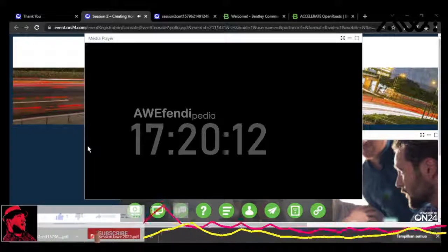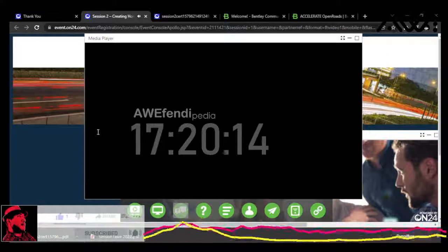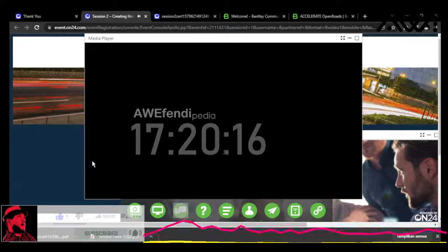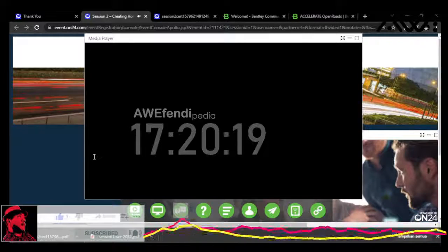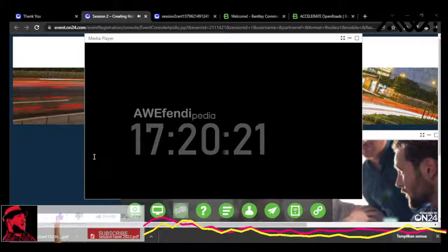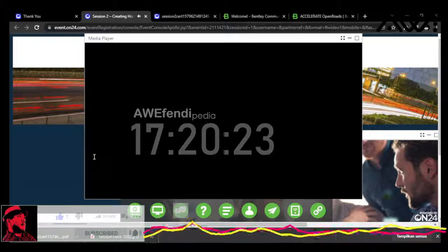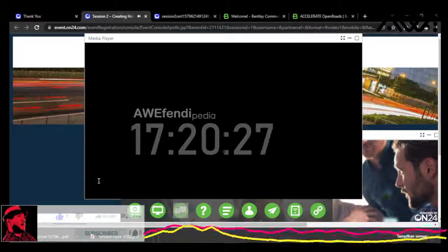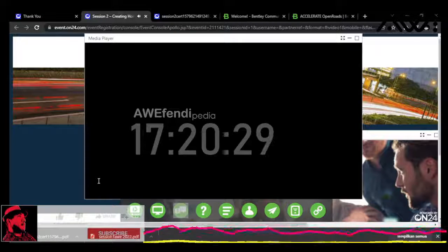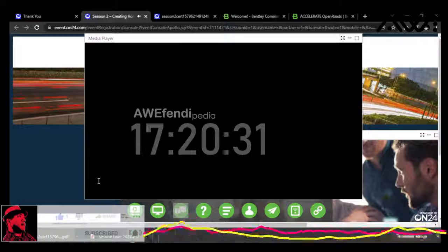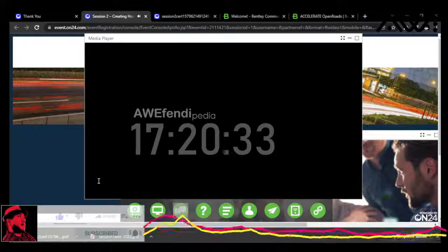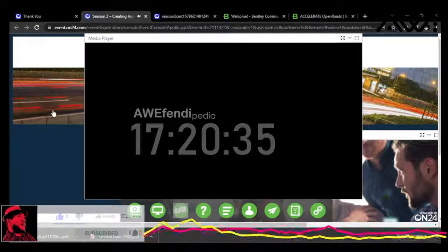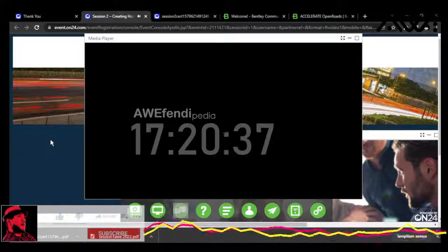And so to begin, again, I go back to my horizontal geometric element to place it. And I'm going to select the start point. Again, I'm doing this graphically. I'm going to zoom into this known monument, and I'm going to just select. Notice there's elements there graphically intersecting one another. I'm going to use the intersection snap and jump to that point, and then begin laying out my first element within, based off, again, my known geometry.